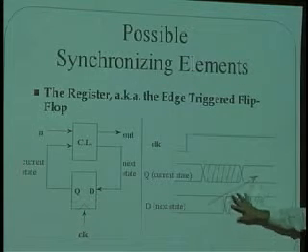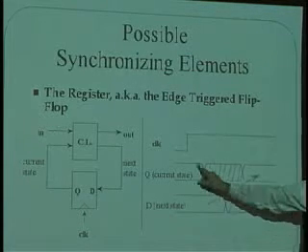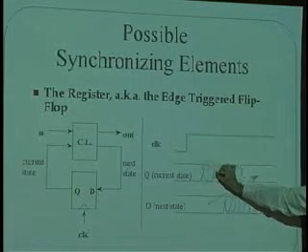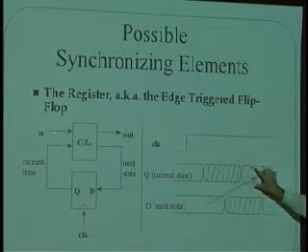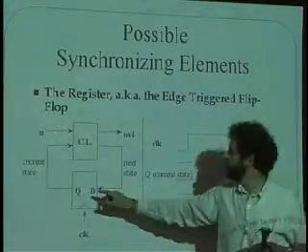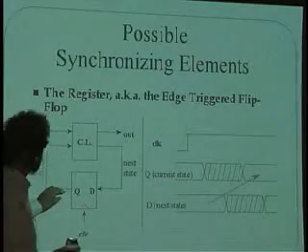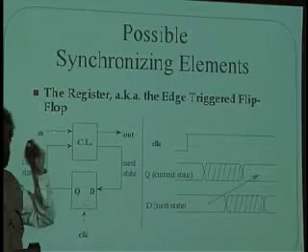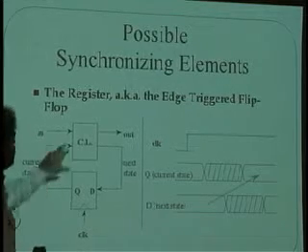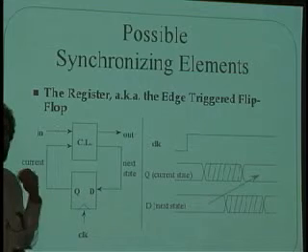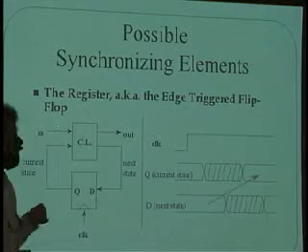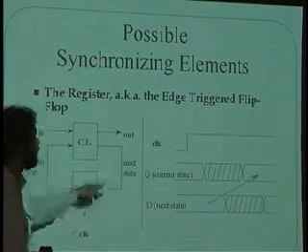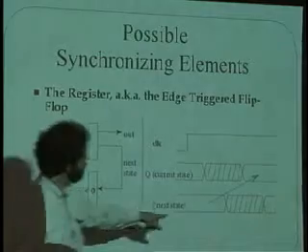Well, right here, this value Q, the current state, switched from its old value to erased. And then finally the new value popped up. Well, if you think about it, that signal saying old value, garbage, and new value went into this logic here as well, into the head of the next person in line. And the logic, just like people, cannot compute instantaneously. It has some delay as well. And so that signal was delayed, saying what the next state is.